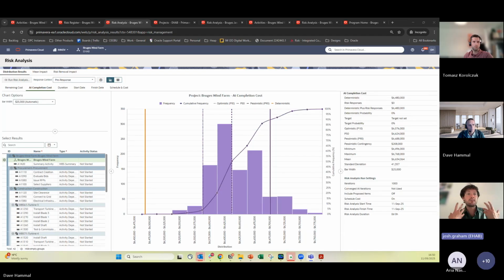So instead of saying my threshold is 10 mil each day, it might be my cumulative threshold is 10 mil for clay, or 7 mil for chalk, or whatever it might be, and we'll create some sort of rough standard.